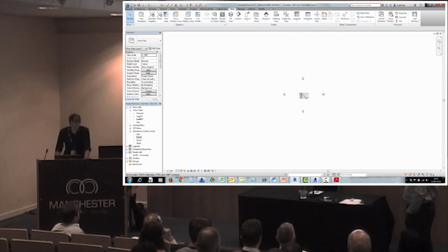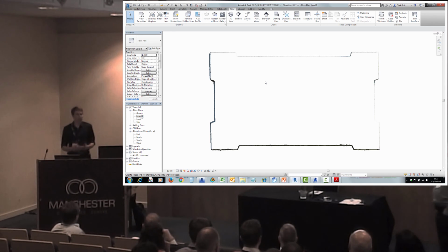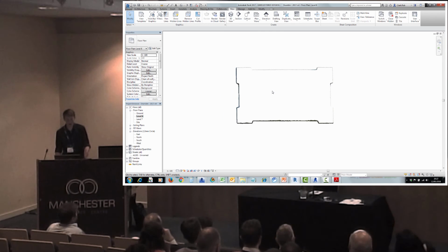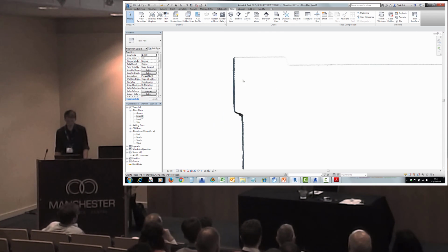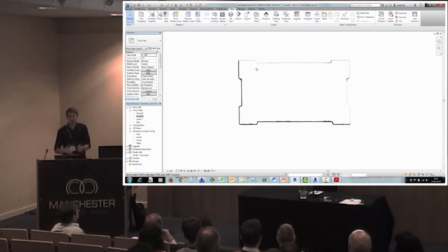Okay. So if I go to level 6, this is halfway through the tower, and you can see there the outline of the tower, which again gives us a really good view of exactly how deep these recesses are, how wide each pier is, how wide the tower is, and I can view that at any point up and down the tower, so I can see how far the panels stick out and deviate. Again, as you would with a point cloud. The only difference here is there's a little bit of blur on the lines because it's photogrammetry, not quite as accurate and as many points as laser scanning. You lose a bit of that detail, but for us, we wanted a rough model. If it was plus or minus a little bit, it wasn't too much of a problem.